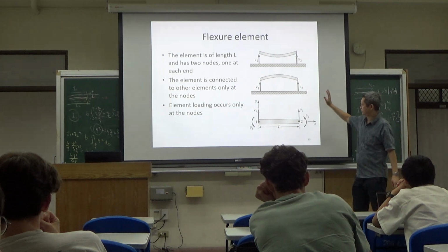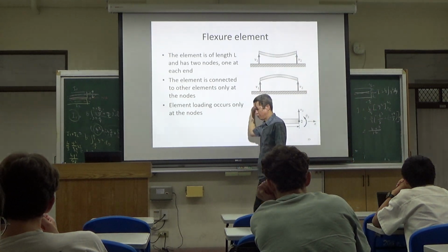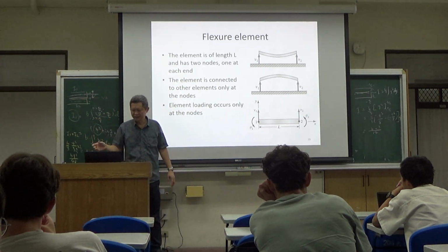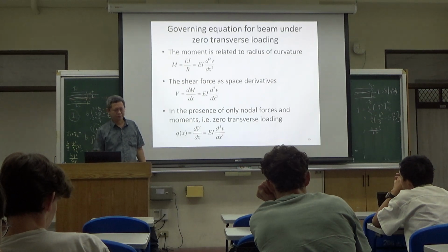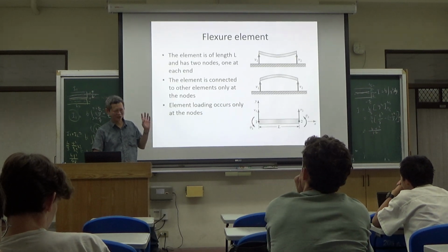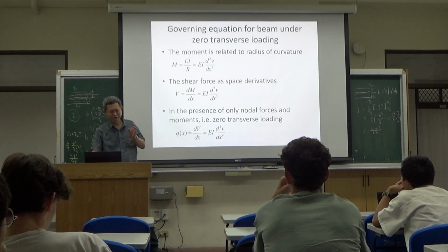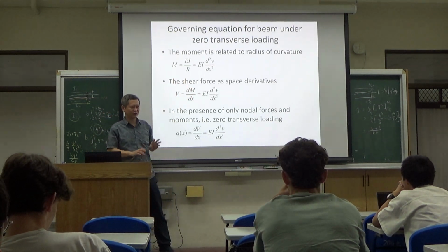I want to stick to one convention. All displacement is vertically upward positive. All bending angle is counterclockwise positive. That's it. Always positive. But then your formula got changed. Your convention for finite element is different from the convention of beam bending theory. But we can do it consistently.